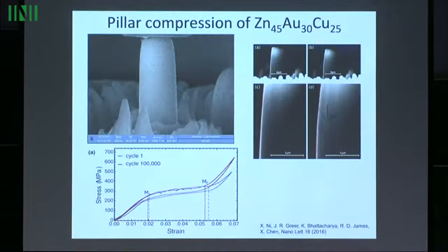Good. Here's another. It's always more demanding to stress-induce the phase transformation. This has very much to do with the first lecture, where I had this energy of the loading device. So you have this variational problem. You minimize the free energy of the material, but if it's being loaded, of course, as Gibbs would say, you have to close the system, include in your system also the energy of the loading device, and minimize the sum of those. And so because of that, you have an effect which is a well-known effect.